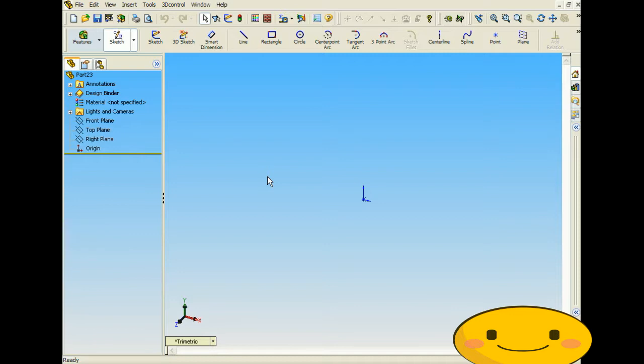So really it's the same, there's just a couple differences and drawbacks. The only drawback I really see compared to the other ones is that when you're using the linear pattern sketch, you're only able to do it about the X and Y and then rotate it whichever way you want it to be. Compared to when you use the linear pattern feature, you're able to just click a line and it'll feature along that line, so it can be on an angle or whatever it is.